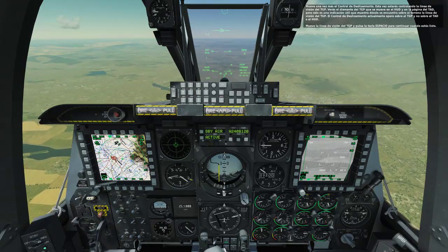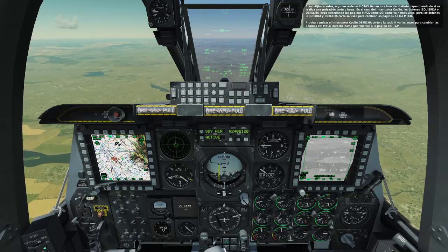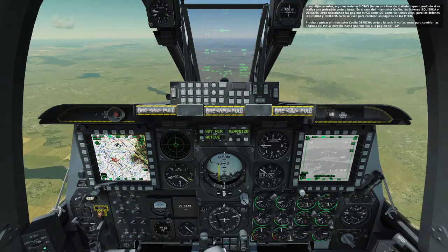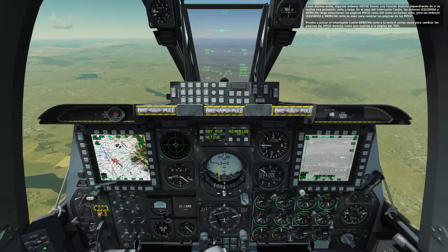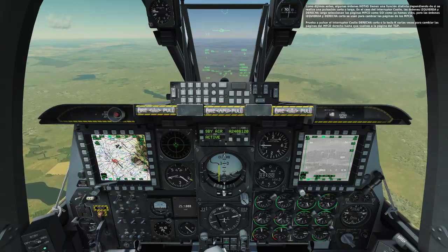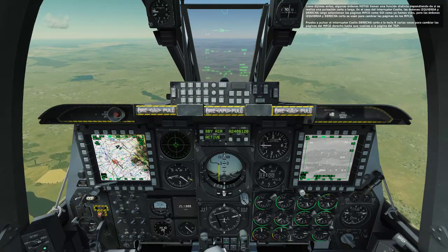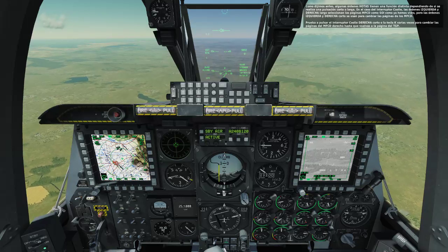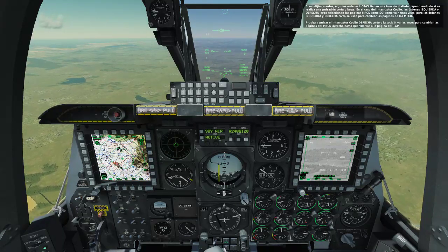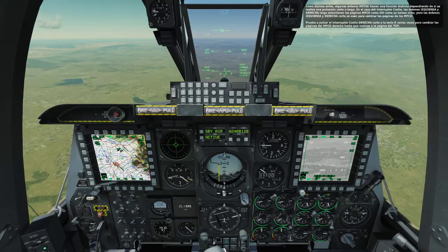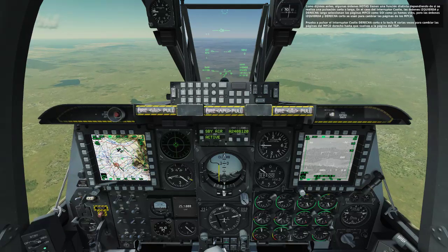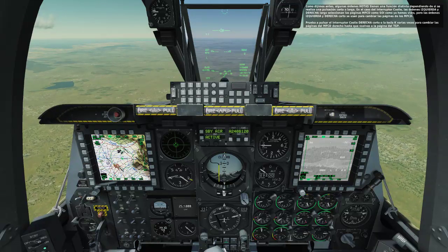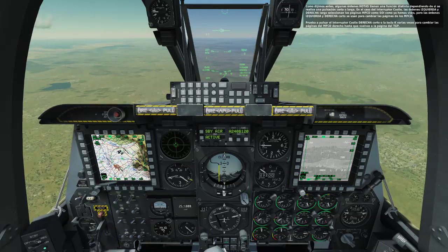As we said earlier, some HOTAS commands have a different function depending on whether a short or long press is performed. In the case of the coolie switch, long left and right commands set the MFCD pages as SOI as we've seen, but short left and right commands can be used to cycle the MFCD pages. Try pressing the coolie switch right short command or K key on the keyboard a few times to cycle the right MFCD pages until you return to the TGP page.